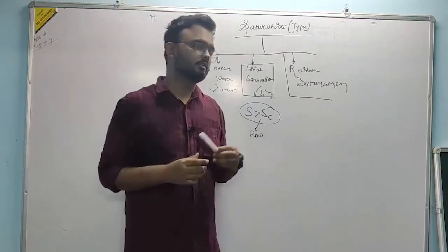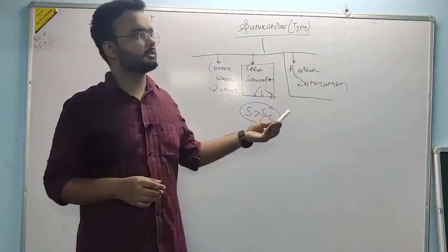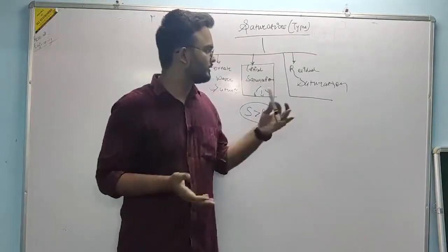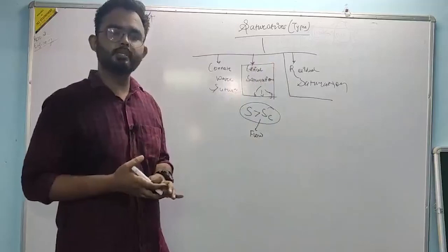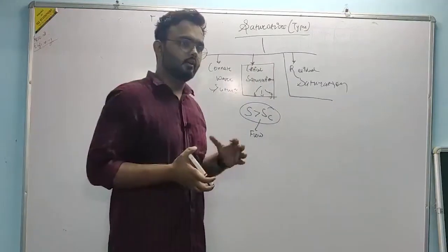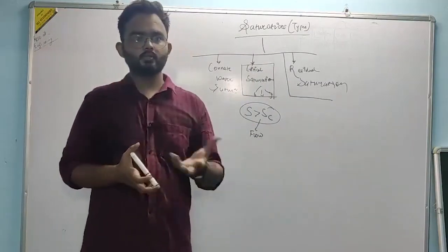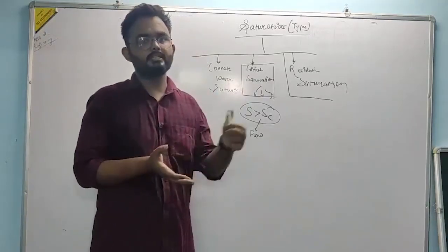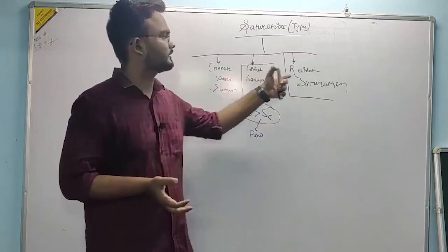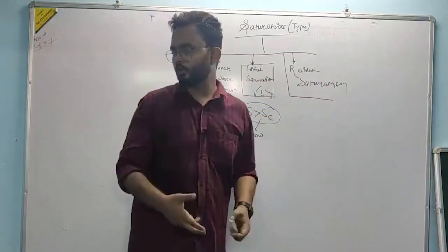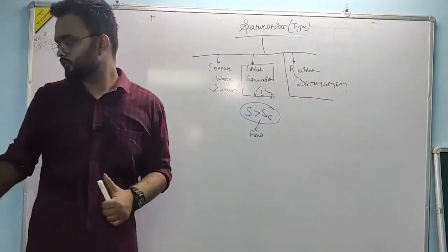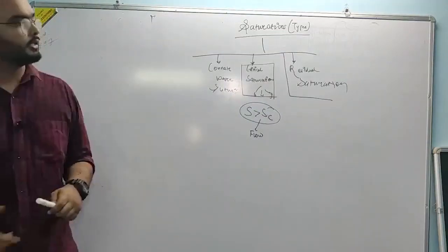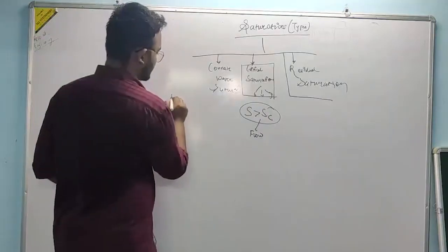Most people like to call it the remaining oil saturation, that's another nuance, but right now residual saturation is a saturation at which the oil or any particular phase becomes discontinuous again and cannot flow anymore. At the end is what we are talking about. This is at the start and this is at the end. Okay, so I hope you now get a clear picture of how saturations are. Now there's one more thing. It's called the movable oil saturation.